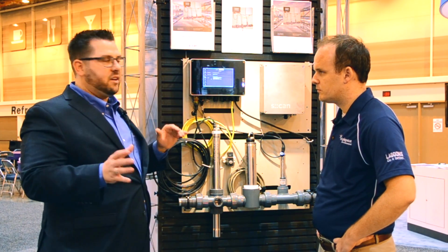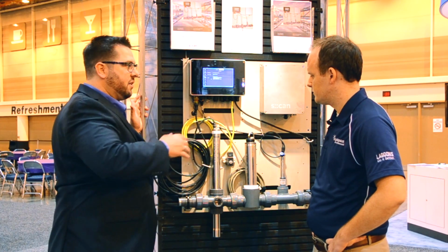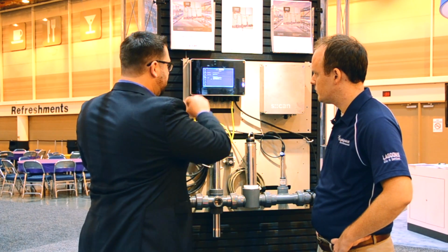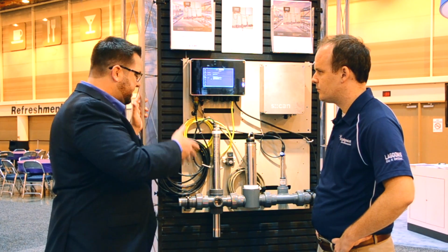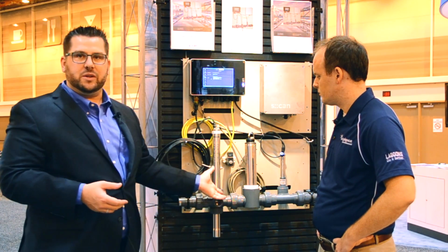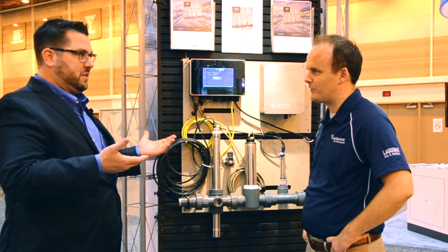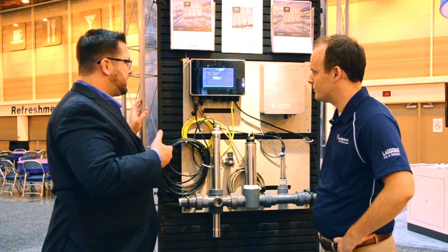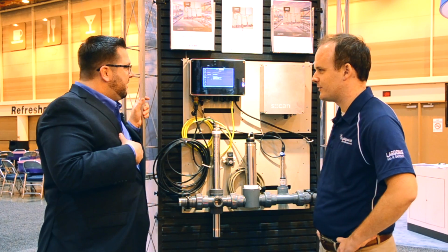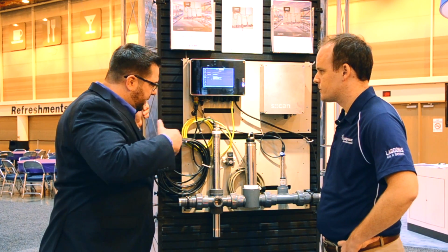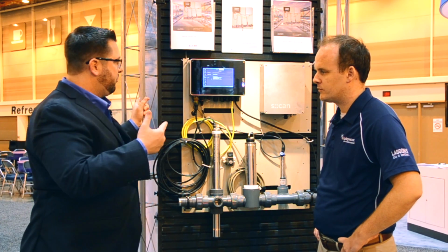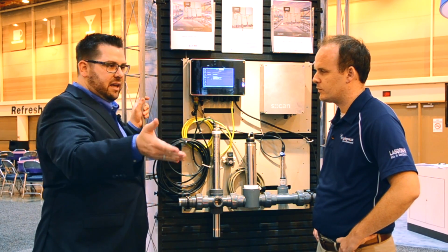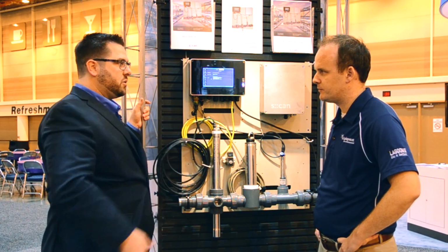It runs self-diagnostics, and it knows that the sensor is okay. There are no issues there, but there is a parameter error. There's something wrong with the installation. In this case, there's no water going through the station, so it's notifying you that there's an issue. There's no water, or the wrong medium. So all the sensors run self-diagnostics, so that if you have an issue at a remote site, you can look in real time, see an error, and know whether you have an issue with your sensor or with your installation.